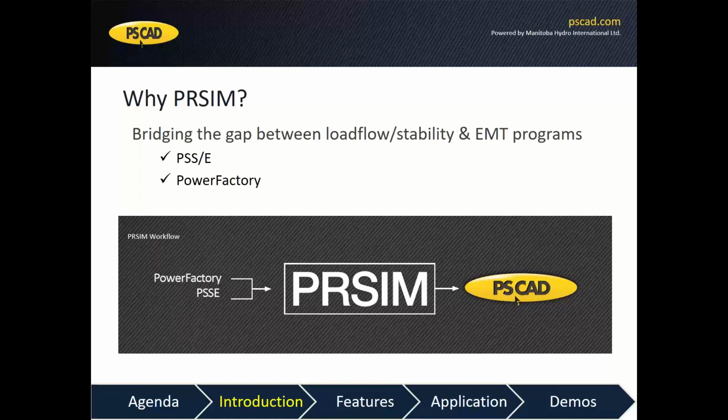It's there to bridge this gap, and our development team has come up with the Power System Importer tool, known as PRSIM, to facilitate importing data from PSS/E or PowerFactory as two standard network database formats. You may think of it as an intermediary platform where you can dump your load flow information and it will do the necessary sanitation and post-processing to make it ready for PSCAD studies.